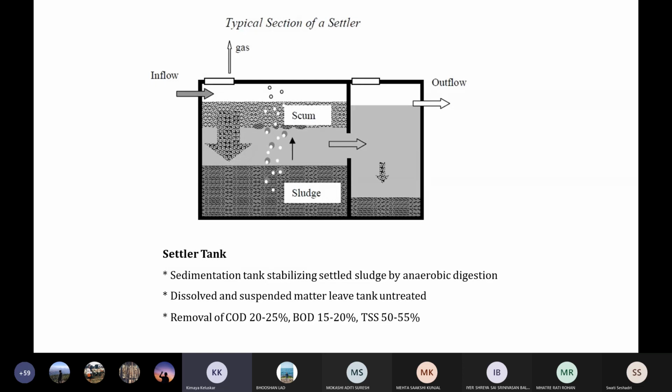But just understand that at the end of every screening process, there are certain standards which are prescribed by the government. It's basically the CPCB, the Central Pollution Control Board, which gives you these standards, and you have to meet them. The people maintaining the systems will have to take these readings, monitor them, and also submit them to the municipal corporation to ensure that whatever water you're recycling meets certain standards, and doesn't harm any human being or any lives. Next.